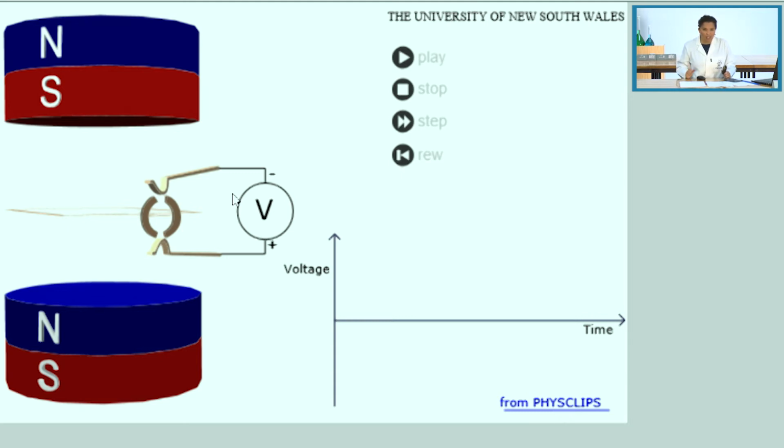Is it an AC generator? Well, let's see. Are there two little rings here? Absolutely not. Do I see a hamburger roll without a patty? Absolutely yes. I can see the split ring commutator, and you can beautifully see the top and the bottom and the gap in the middle. They are connected by a brush on the top and a brush at the bottom, and that connects to the coil or the armature in the circuit. That coil is sandwiched between magnets.